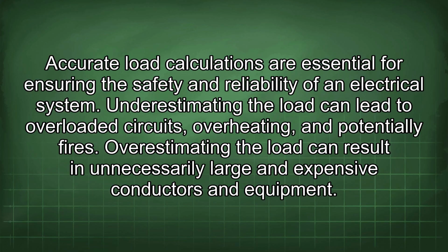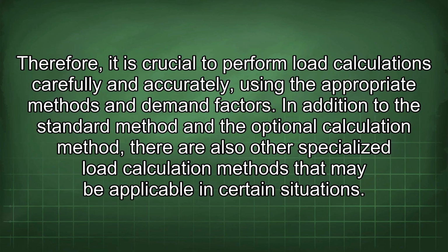Underestimating the load can lead to overloaded circuits, overheating, and potentially fires. Overestimating the load can result in unnecessarily large and expensive conductors and equipment. Therefore, it is crucial to perform load calculations carefully and accurately, using the appropriate methods and demand factors.